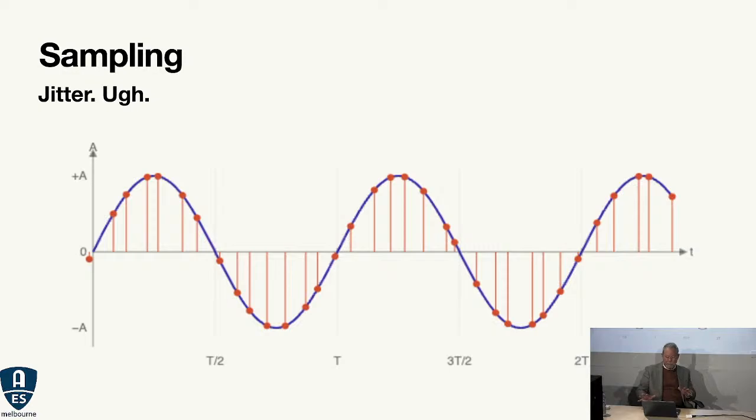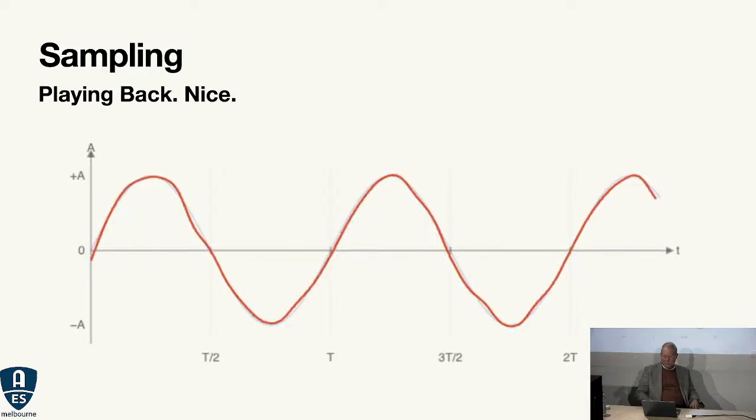So if we take that jittery sample and we've recorded those and we decide we're going to play this back, what might that look like? So that's literally as if it were played back with the sample playback in exactly the right place. And this is the effect of jitter. This is an extreme amount of jitter, which I had to do so you could actually see it, because basically at low levels you can't see it in a waveform, and it actually becomes quite hard to measure.